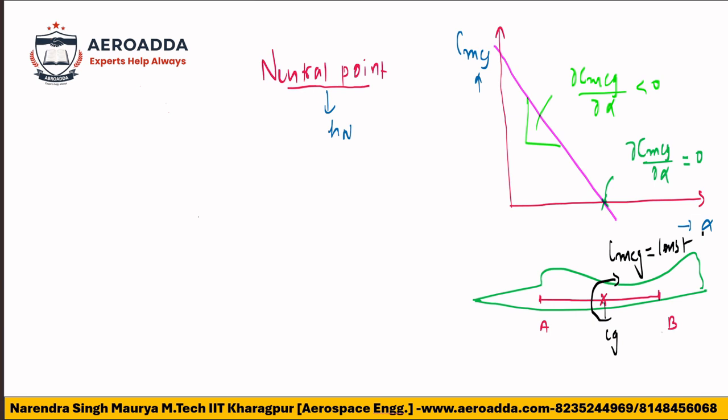If it is varying about CG, sometimes 200 Newton meter, sometimes 20 Newton meter, sometimes 250 Newton meter, sometimes positive or negative, then it means there is motion about the lateral axis, and it will be pitch up, pitch down, continuously. If the moment is constant, it will be neutral. It is not going up, it is not going down. I hope you are getting my point.